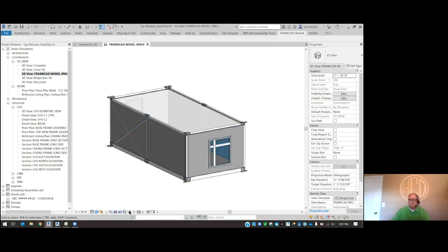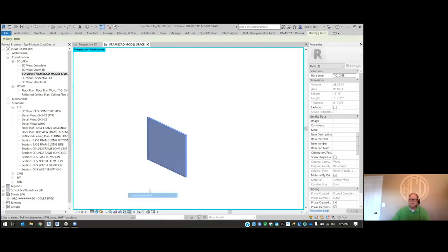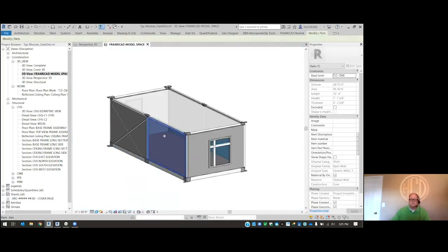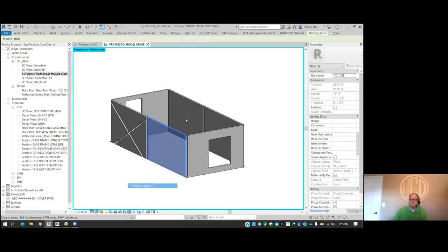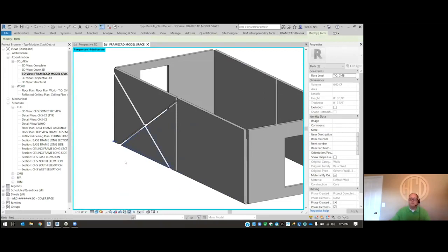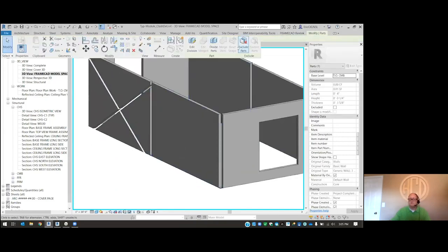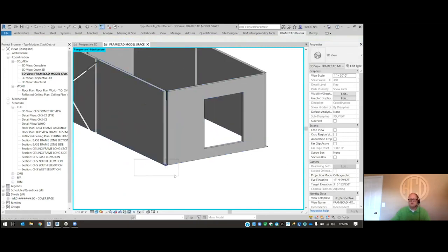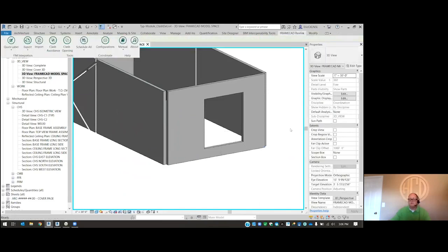Now we can select some of these elements and isolate them. We can isolate the category. Because of the modeling, there have been a few parts that have been included here that we need to exclude. So we can exclude these few parts here so they don't mess our import up. That's just where differences in the various structural components and the modeling have come together.